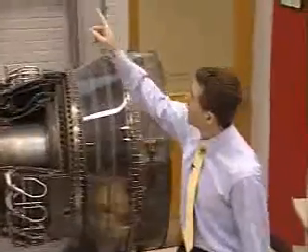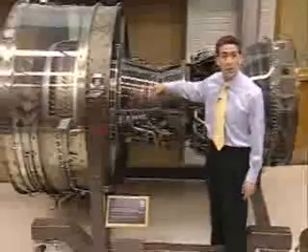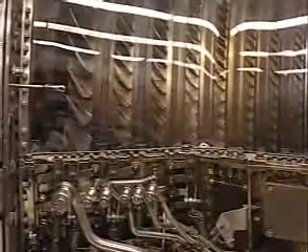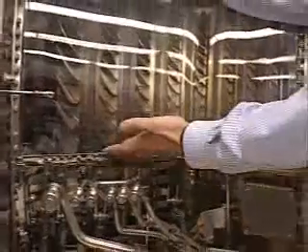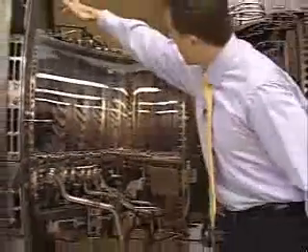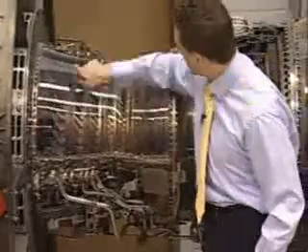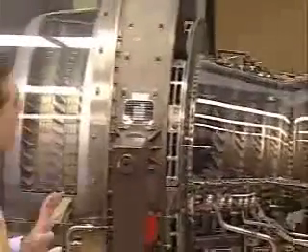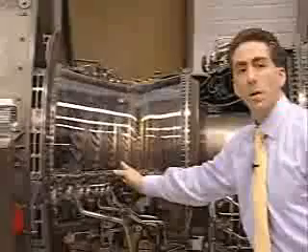And I just want to point out in this picture up here, when you look at this engine, the various things that you're looking at. When this engine spins, you see the rotating blades, right? These are called rotors, so those are labeled with R's on that diagram. What you don't see, because they've been cut away, is that in between each one of those rotating blades is a stationary set of blades called stators. So the construction is a rotating blade row, a stationary blade row, rotating, stationary, back and forth.